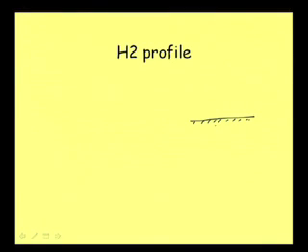Now, when we are talking about horizontal slope or horizontal bed, meaning SB equal to 0, over the horizontal bed we get the critical depth line here, that is, this depth is YC, and we know that on horizontal slope YN is at infinity. So, we do not know where our normal depth line will be, or rather we know that it is at an infinite distance.